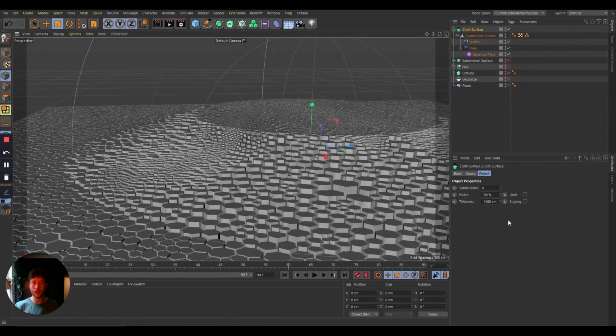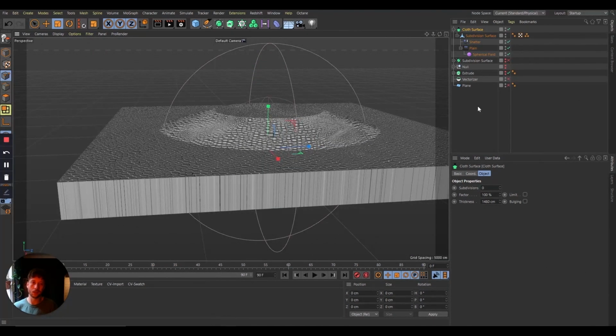And the reason I'm doing negative values is because I still want to be able to treat this like a ground plane. If it was positive, all of a sudden my ground plane would be higher than it was when I started, I suppose is the best way to put it. I don't want it to extrude upwards where my ground plane is still here. I want it to extrude downwards, and my ground plane is remaining zeroed out and in the center of our scene. Okay, so let's just make this negative 3000 for the time being.